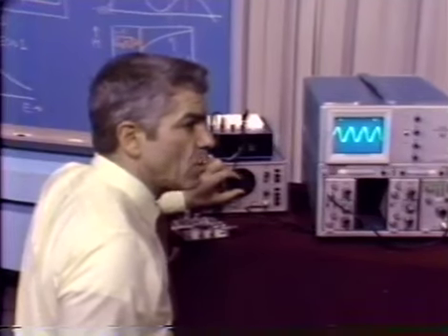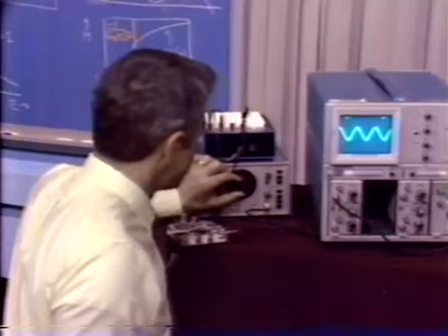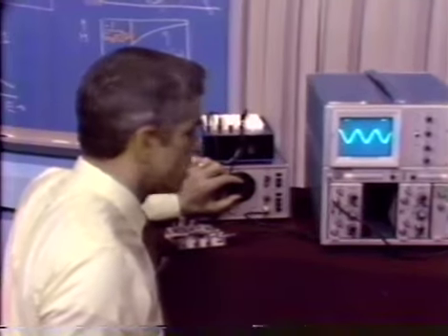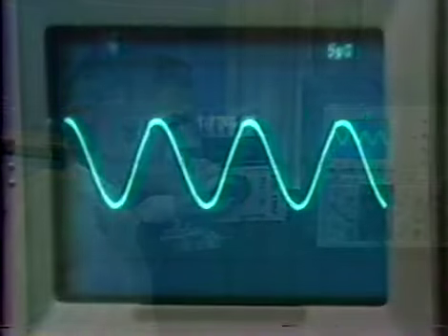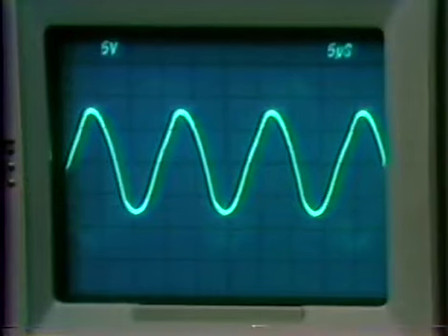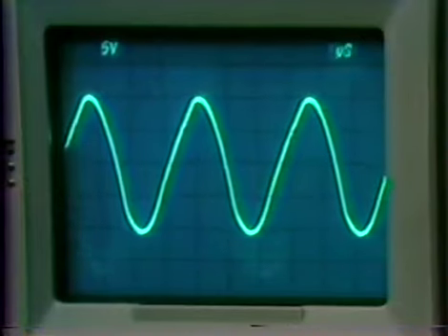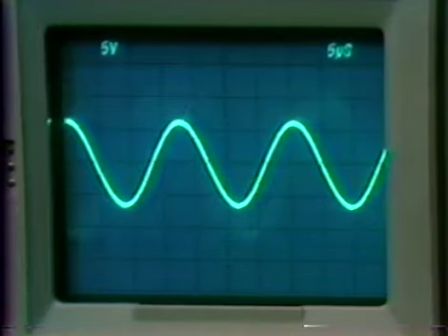I'll now lower the frequency. We get a state that never existed on the way up. And now it pops, and that transition occurs at about 55 kilohertz. So there's a hysteresis in the frequency characteristics. The width of the hysteresis is about 20 kilohertz.